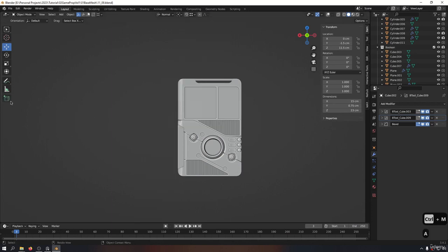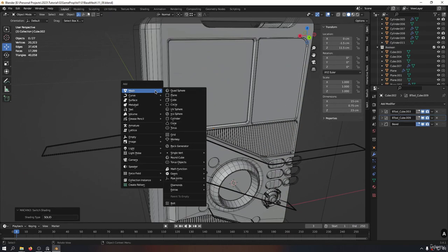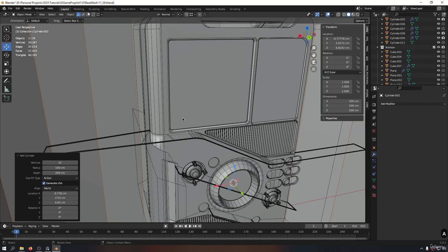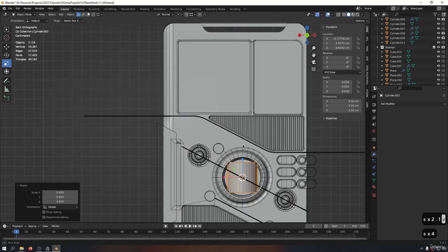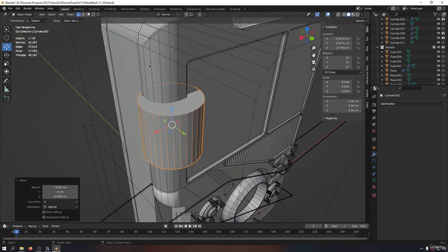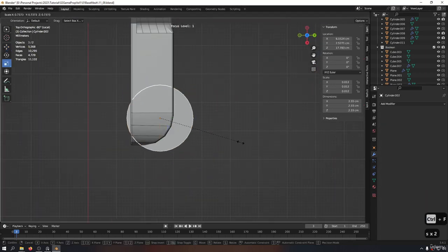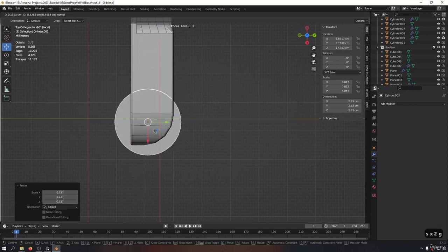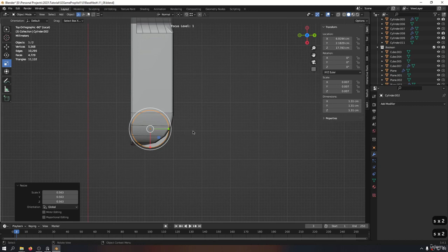And the first thing, we're gonna go and create a cylinder. This time, let's go bring in a normal cylinder and we're gonna bring that to here. So Shift and A, and then we're gonna go bring in a cylinder and let's scale that to 0.1. Okay, like so. Now I'm gonna bring that in here and I'm gonna make it just the same scale as this one is. So let's just take a look and I'm gonna roughly eyeball that to get the design perfect.